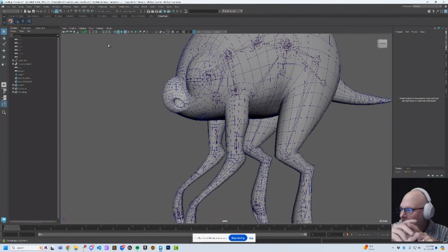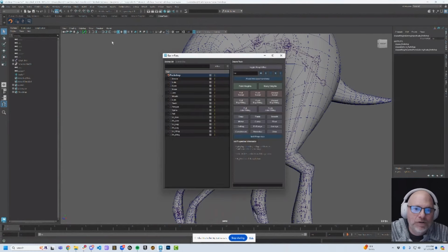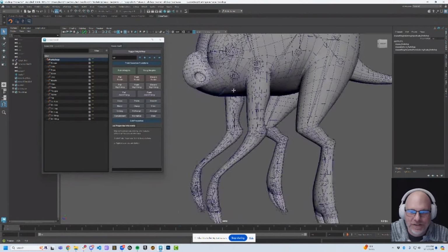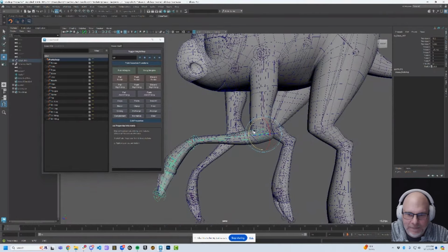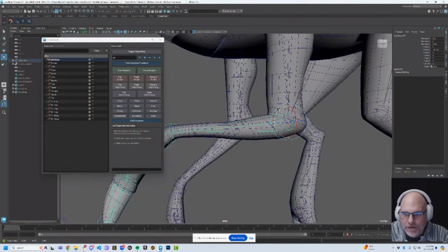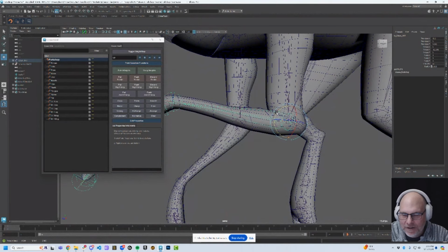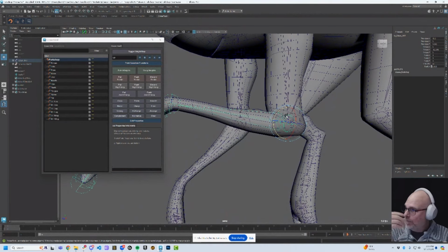So we think about independent weight maps. We looked at it in the context of a face, and we're going to look at that again. But I want to show the elbow. This is something that I think most rigging TDs that have ever had to solve this problem will appreciate, right? If I take this and move that up and down, you can see that I've got that shape in the elbow. That is a weight map and a sculpt. I'm using those pieces together.